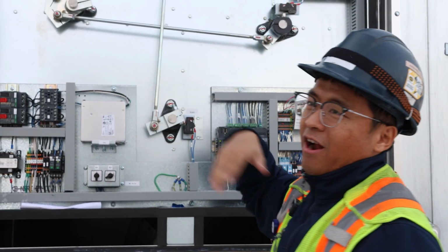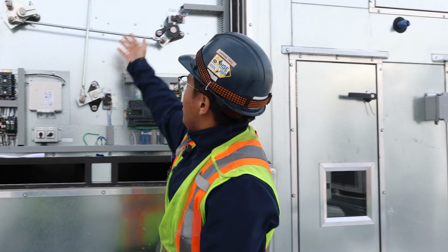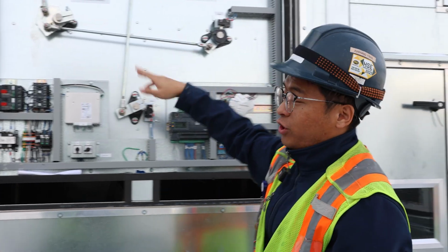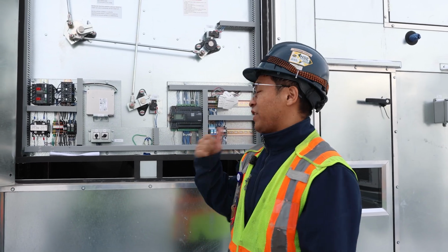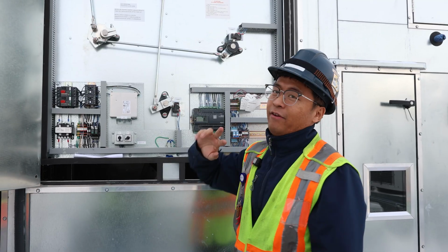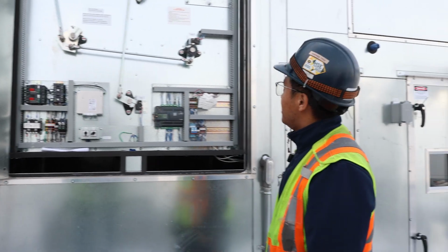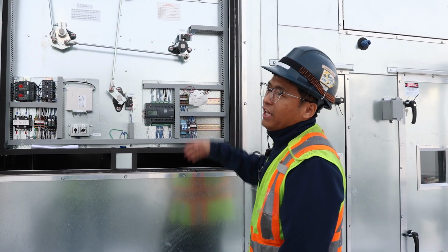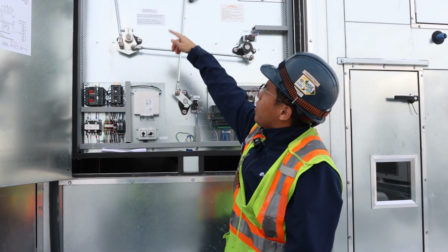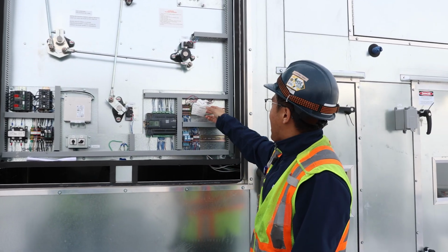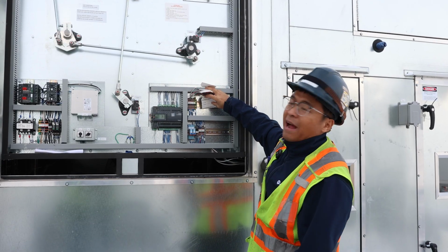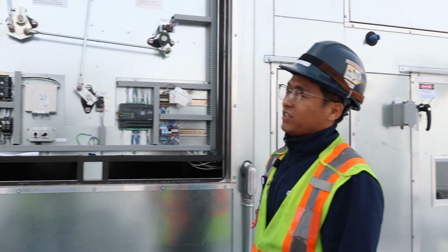So right now we are in the heat recovery mode. Those dampers should switch every 60 seconds. If it's in free cooling mode, they switch every 3 hours. See, it does the switch. If any damper is stuck or end switch didn't make, the unit will be turned off, and we will have the damper alarm. It will show on the BMS.